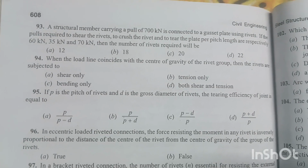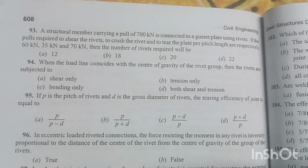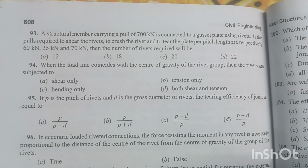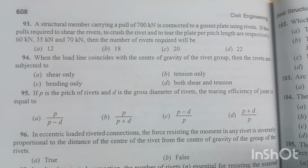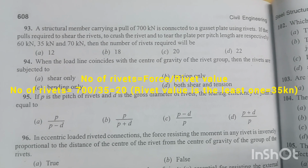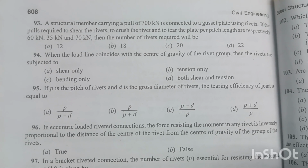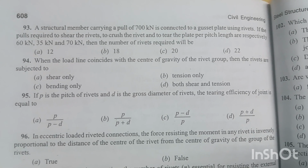Question number 93. A structural member carrying a pull of 700 kN is connected to a gusset plate using rivets. If the pulls required to shear the rivets, to crush the rivet and to tear the plate per pitch length are respectively 60 kN, 35 kN and 70 kN, the number of rivets required will be. We know the number of rivets equals force by rivet value, and the rivet value will be the least among shearing, bearing and tearing, that is equal to 35 kilonewton. Option C is the right answer, 20.